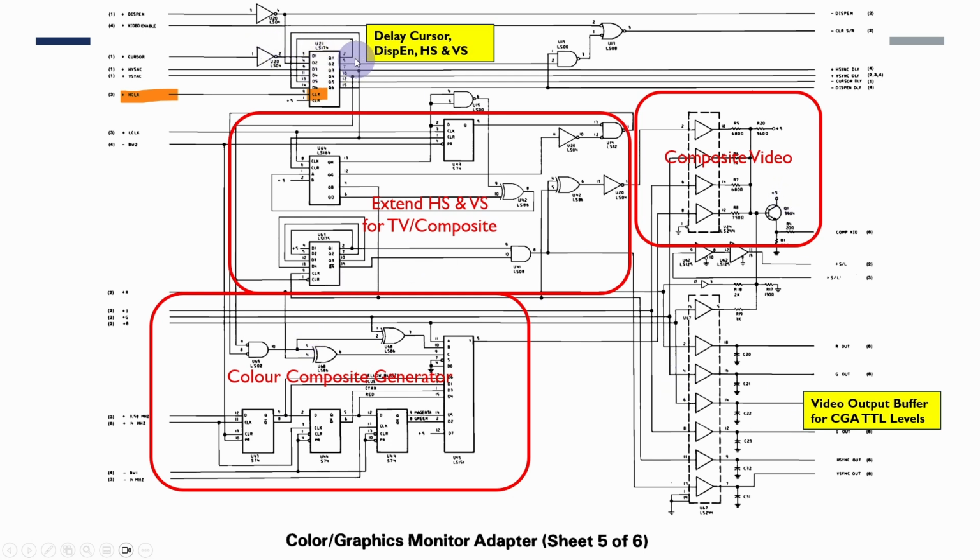There's just a little bit at the top here which is to do with delaying some of these signals by 1 or 2 characters in the character clock. And this is similar to what we've done in the MDA, and the Hitachi chip is able to configure the delays for some of these signals in register configuration rather than needing some hardware.